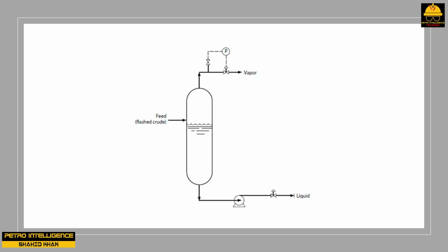During this period, he can crack open the pump discharge valve, push the motor start button, and then slowly accelerate the liquid in the suction line by slowly opening the discharge valve. If he can do all this before the lighter liquid formed at the vapor-liquid interface in the drum reaches the eye of the pump's impeller, then he can start up the pump. Thus, even though we lack the extra available NPSH to satisfy the pump's starting NPSH requirement, he could still start the pump.